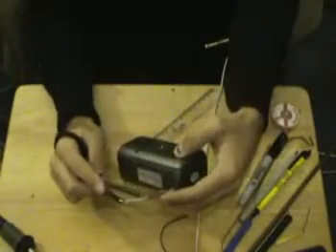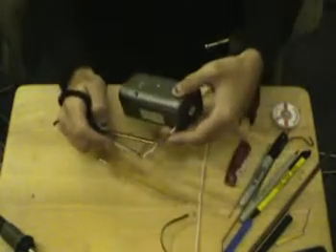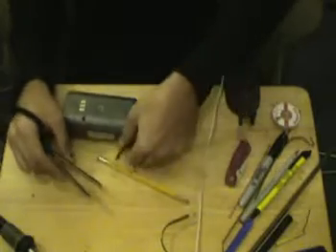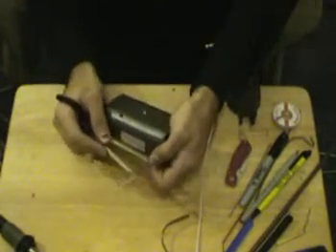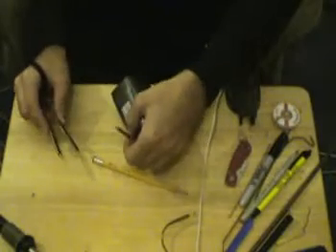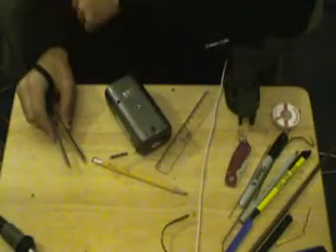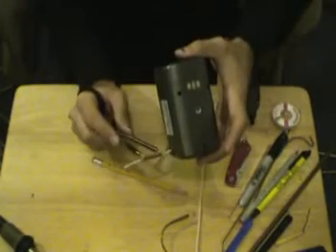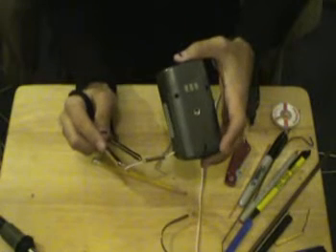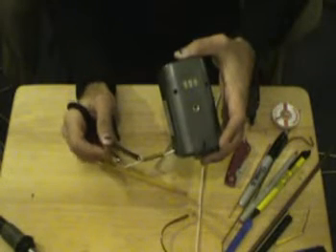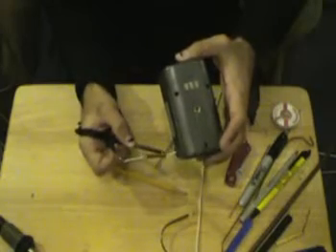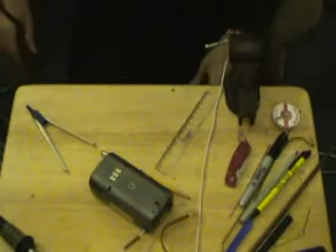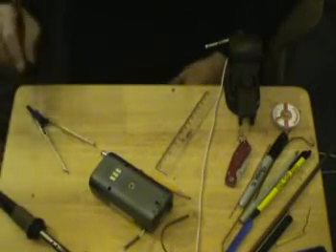So I take my compass, and using it kind of like a caliper, I've measured this, and it turns out to be 2.5 centimeters on both sides. So we got 2.5 centimeters here and 2.5 centimeters there. Doing some math on the wavelength, 2.5 centimeters should come out to about 1/4 wavelength on each side. So this side is quarter wavelength, and this side is quarter wavelength of 2.4 gigahertz. If you expand them both together, that means this is a half wave dipole, because we have 1/4 on each end. Now, you might be asking yourself, well, if that's the case, why can't I make a 2-wave dipole?